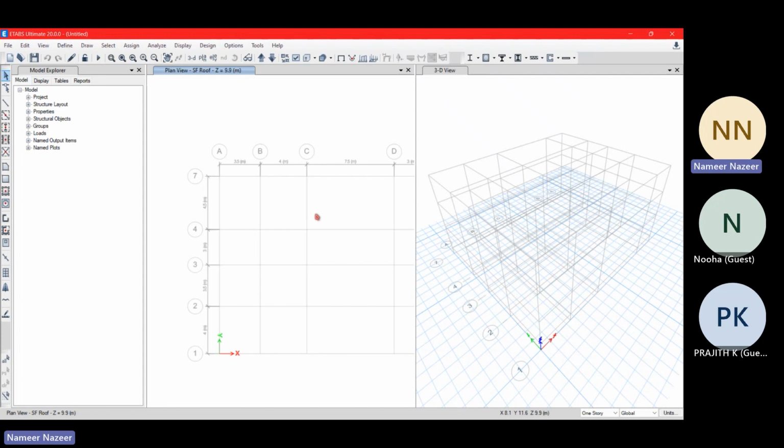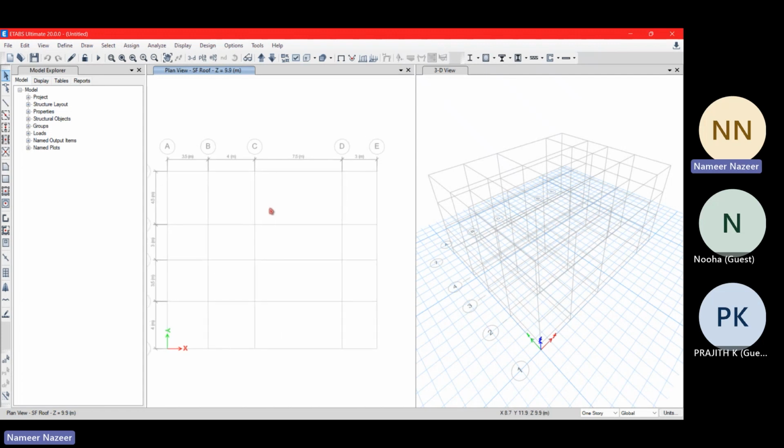Okay, now if I need to edit the grid after modeling, if I have finished all that quick templates, I have finished the model initialization and all, I need to edit the grid data. Here it is 7.5 meter, right? I don't need to provide 7.5 meter.